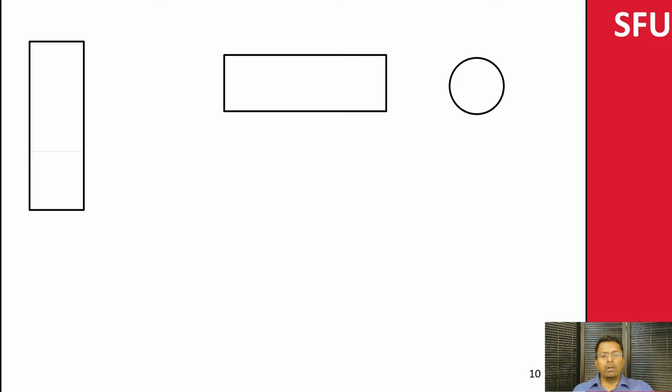Here, notice this is all going to be thick, which is the outer feature. This would be the profile that I see. And then there is this line that I don't actually see, which is at the back. If you think about it, it's right behind over here. In order to denote that, I would use the hidden lines, or the dashed lines, to mark the hidden feature.